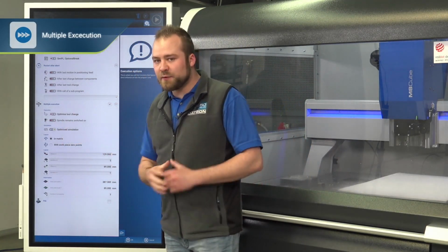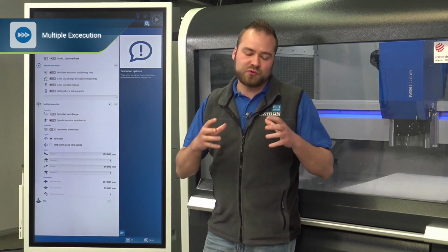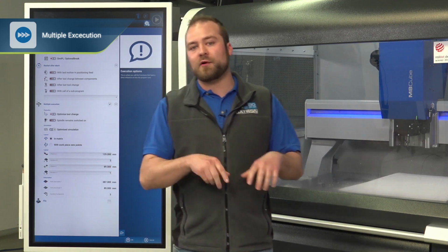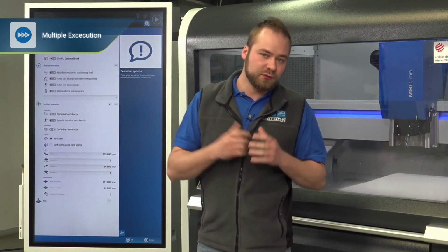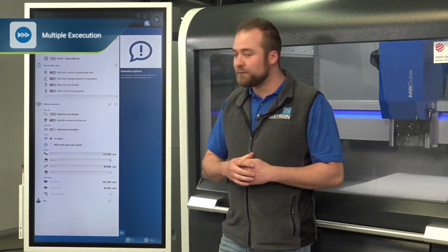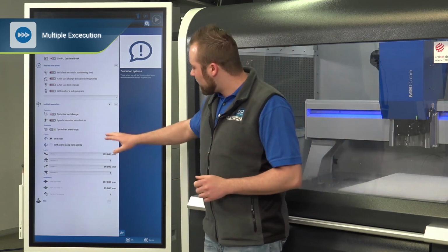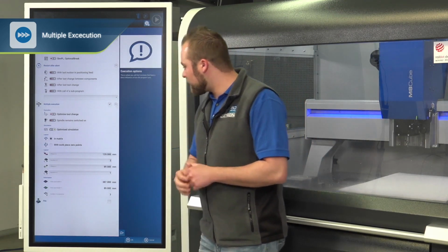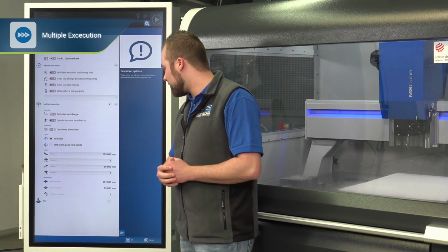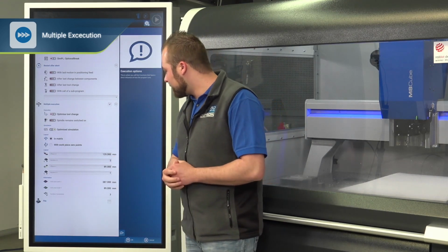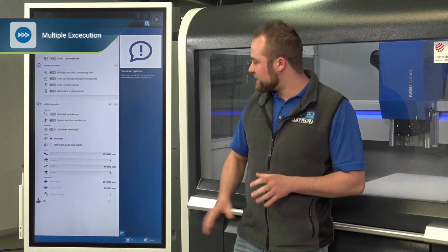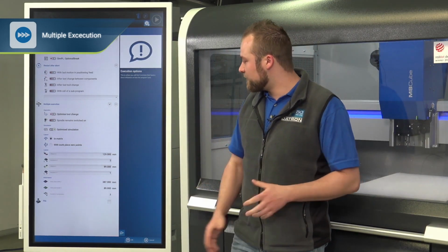That means we can do all operations with the same tool firstly on all of our parts. So we save the tool changing, and that means we save working time at this point. It is very easy. We have to set up a layout, so we have an offset in X of just 120, and in this case I will do just 3 more parts. You can also do this by setting zero points, but in this case we just do it with a layout.